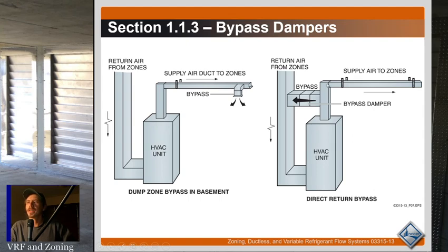So as you can see, your supply air comes out of the unit, goes to the space, to all your zones, and then you've got the bypass damper there that will just short cycle from supply to return. Now this still sucks, alright? Bypassing air like this, obviously, say you got a furnace running full tilt. It's a single stage furnace or something like that.